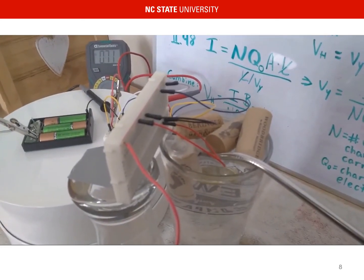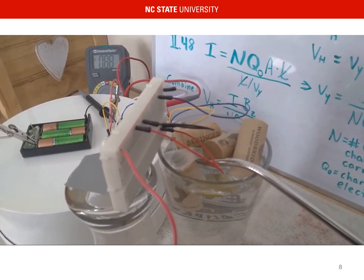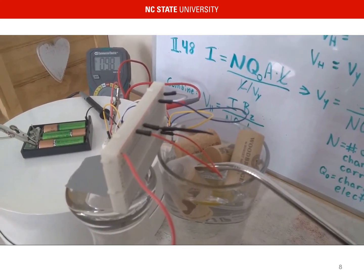Here's a demonstration using another sensor with a different sensitivity level and magnet orientation. The sensor is located above the glass of water in this setup and the magnet is taped to the top of the float. As the water level drops, we see the voltage increases.